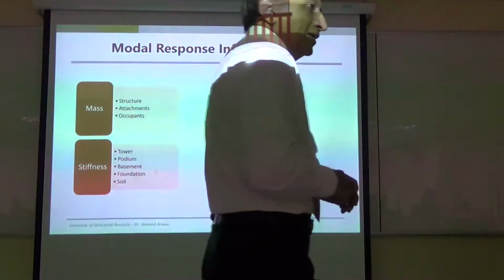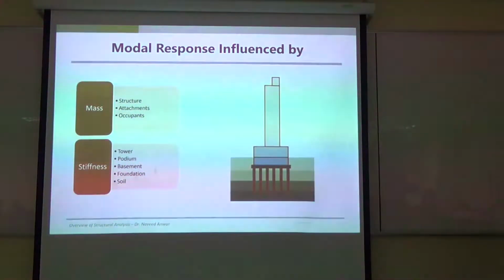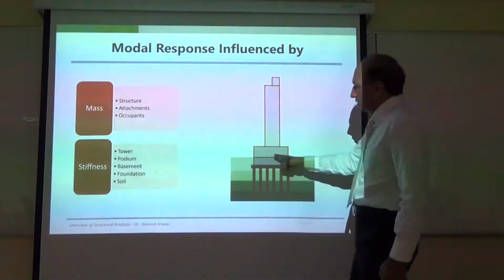And then if somebody doesn't know this, they will think, I modeled the building and fixed all the foundation at the column base, I'm getting good modal properties. No. Because the real building will be much different from that. And what is the effect of that? A lot of forces, displacements and everything will be changed because of the change in the modal properties. So you are actually working with the wrong numbers. So a complete model requires everything.